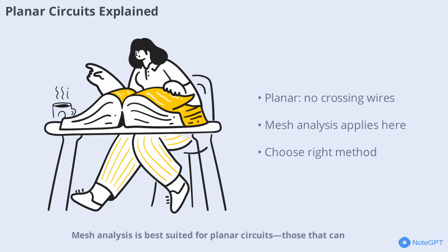Mesh analysis is best suited for planar circuits, those that can be drawn on a flat surface without any wires crossing. Most basic circuits you'll encounter are planar, which makes mesh analysis widely applicable. If a circuit isn't planar, other methods like nodal analysis might be more appropriate. Understanding the type of circuit you're dealing with helps you choose the right analysis technique and avoid unnecessary complication.